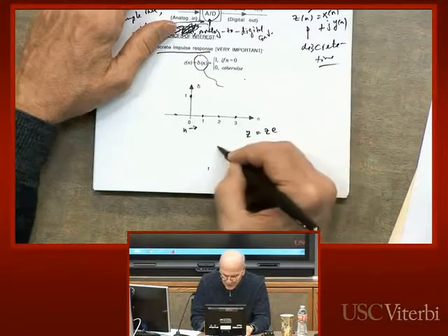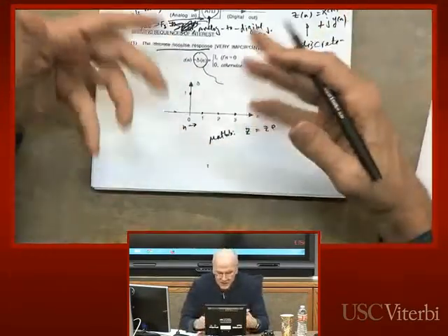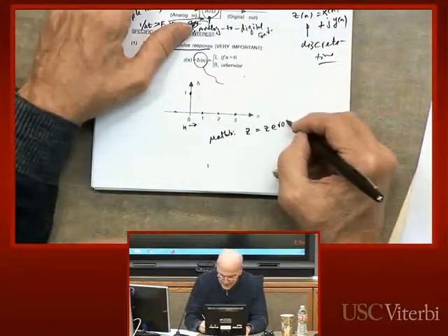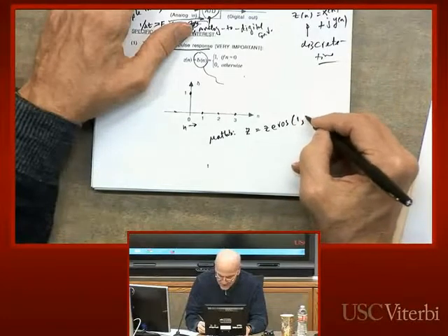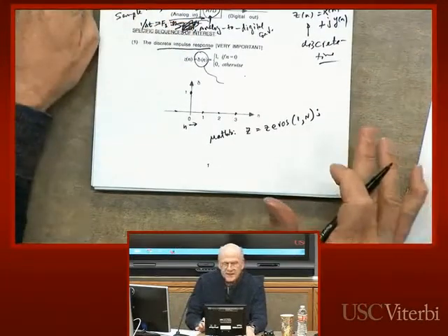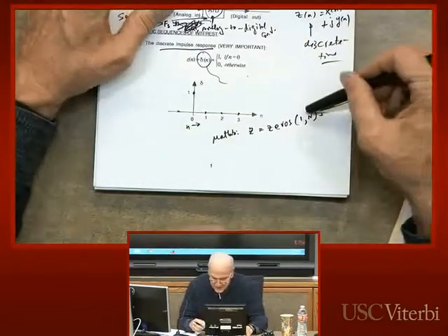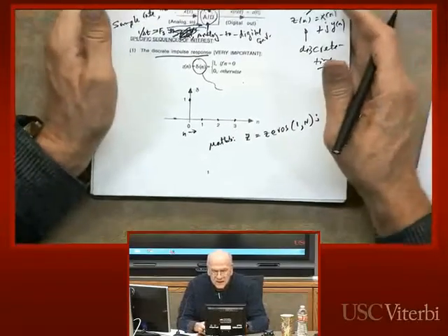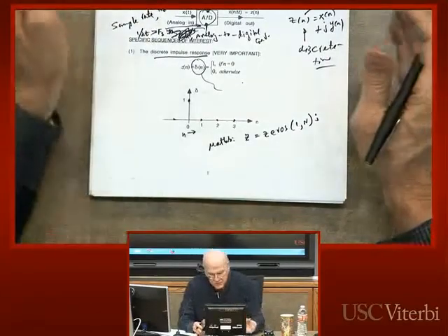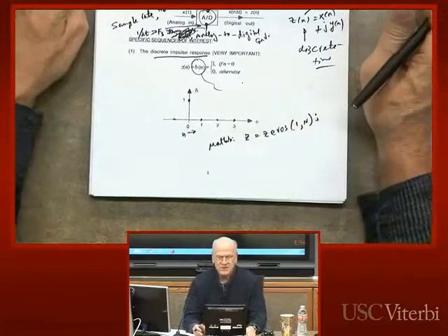What I do typically in Matlab, if I wanted to generate this, because obviously in this class you will need at some point or other to generate this impulse response to probe digital filters, is use these commands. These are actual Matlab commands, where n is the length of the impulse response. You will find out in Matlab that n sometimes needs to be pretty large to see the full extent of the impulse response, especially if you're trying to estimate the impulse response of a digital filter.